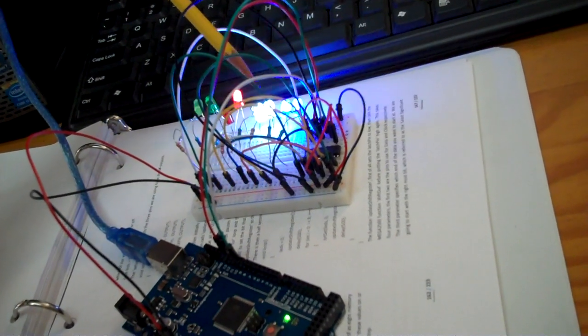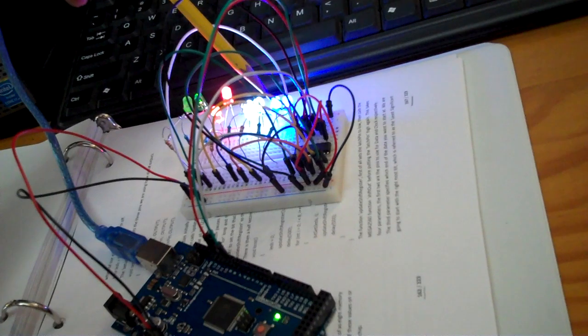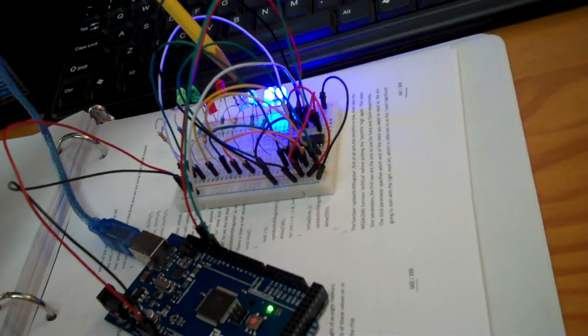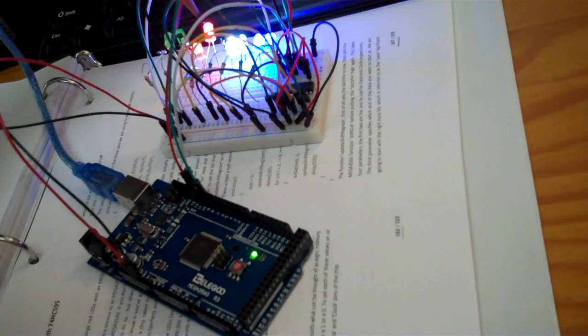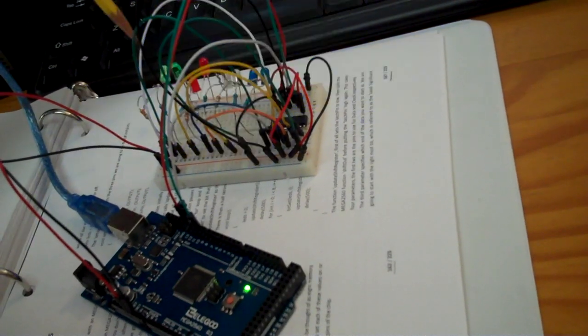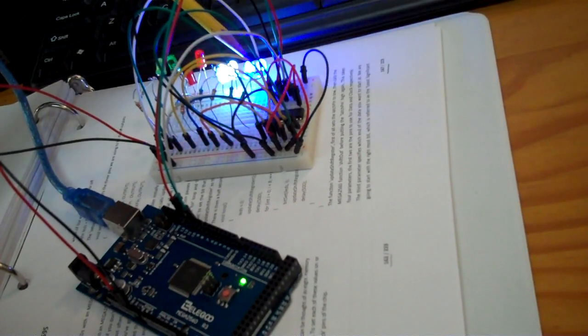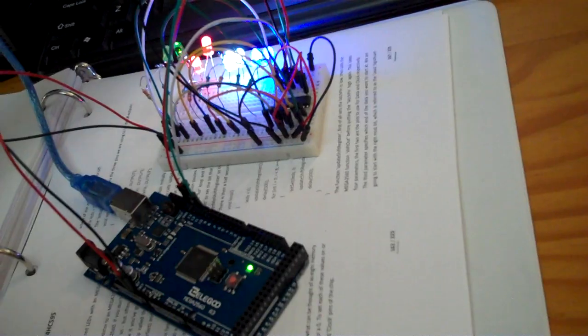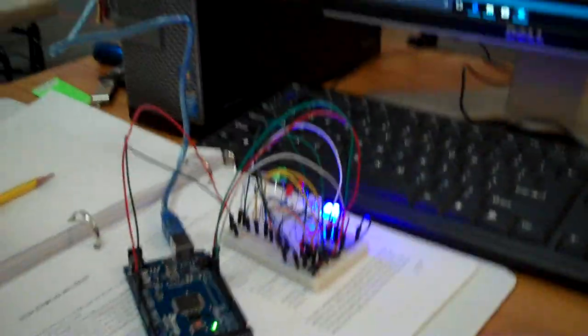The latch then latches in a logic 1 and turns this light on. Incrementing, which was part of the program, will go to the successive lights and go all the way out. Once it hits 8, it recycles back and goes back to 1. Very interesting way of taking a look at serial in data and watching it go to a parallel output.